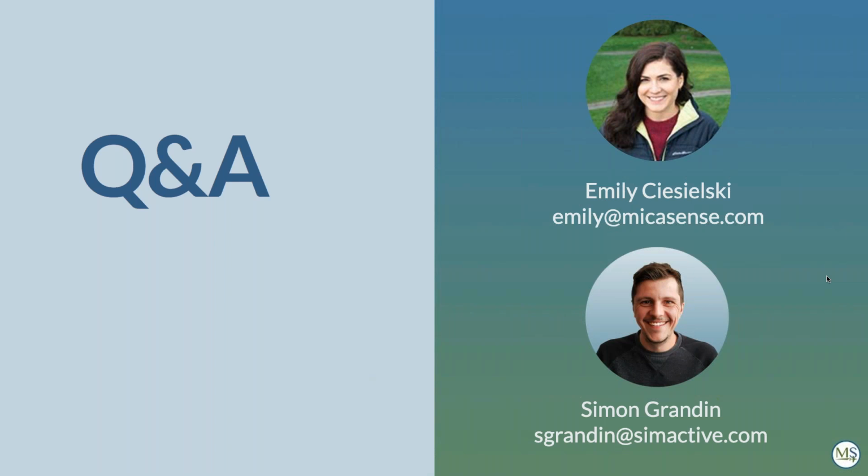We're going to take various imagery around the project and try to find some common alignment parameters, and we'll apply those parameters throughout the project. So it has only a slight impact from the flight configuration that you have. Cool. And I would add to that, generally if you're using one of our sensors, 15 meters would be the lowest that we'd recommend going. And we've been able to process imagery from that height and align fine.